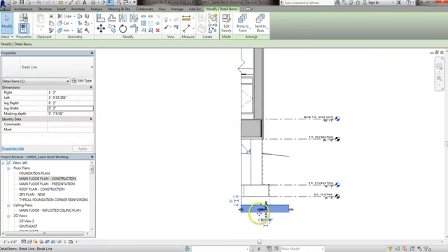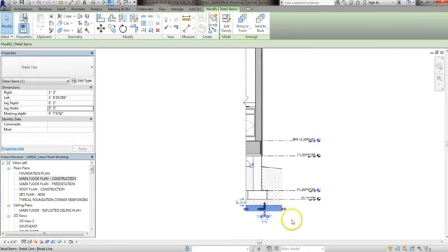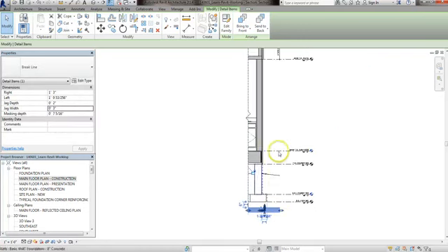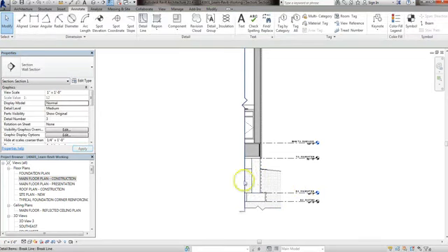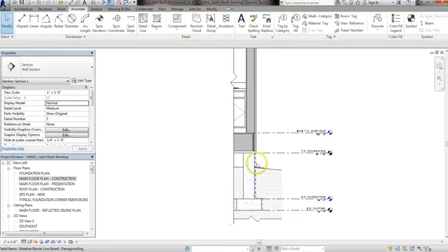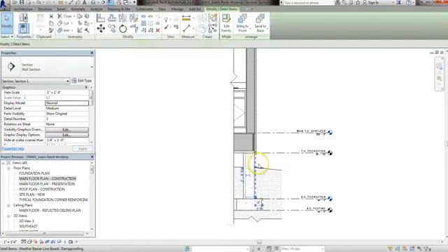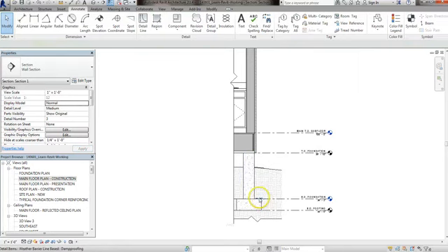And to edit these sizes, because sometimes they're too small, sometimes they're too big, if you're making this section, make sure your scale is 1 inch to 1 foot. Right here you can change it. I think I have it at 9 and 4. Let's see, might be a little bit bigger, but that works for us. Make another one right there. And let's start putting things in.